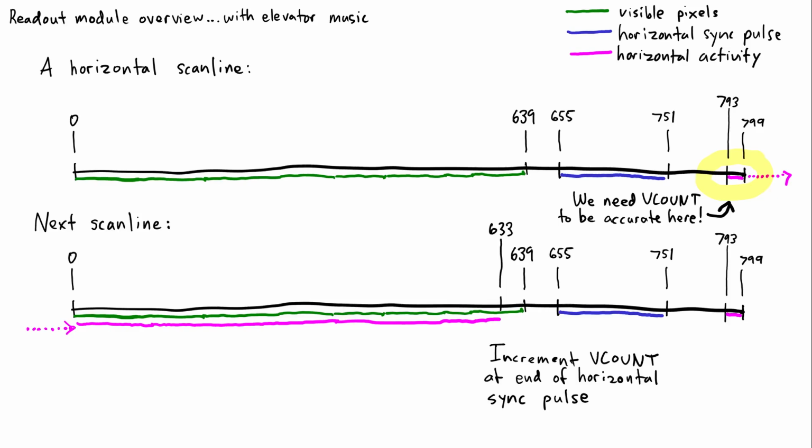If we waited until the end of the scan line to increment the vertical count, we would be guaranteed to render the wrong block of pixels in the character glyph for the first column of characters displayed. Looking back at my failed attempts to implement a VGA text mode using an FPGA, I'm fairly certain I made exactly that mistake, so I'm correcting it in this project.